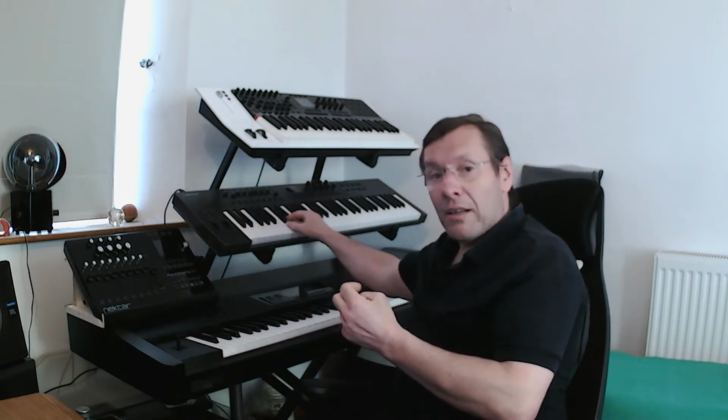But again, with CV, with note and gate data, if I hit, it doesn't matter what key I hit, say I hit that C there, we'll get a CV value, and that value will be sent down the wire. Now when I release the keyboard, in MIDI world, it'll actually send a release note out. But in the CV world, that C or CV note data is still holding that C value. That C value doesn't drop down to 0. It will hold it indefinitely until it gets another value in, and then it will change it to whatever new note I play.